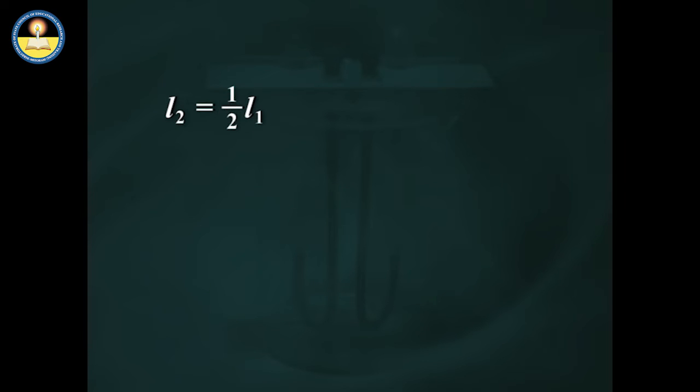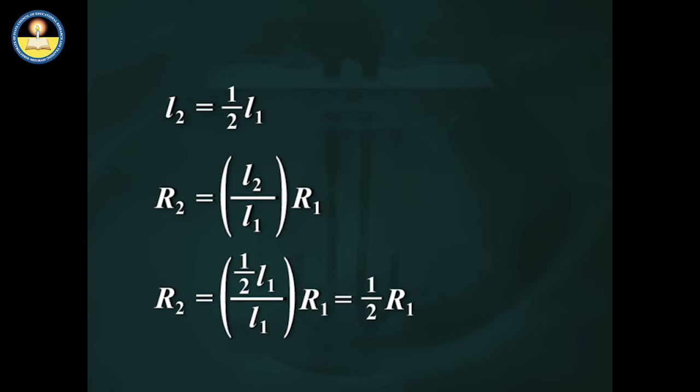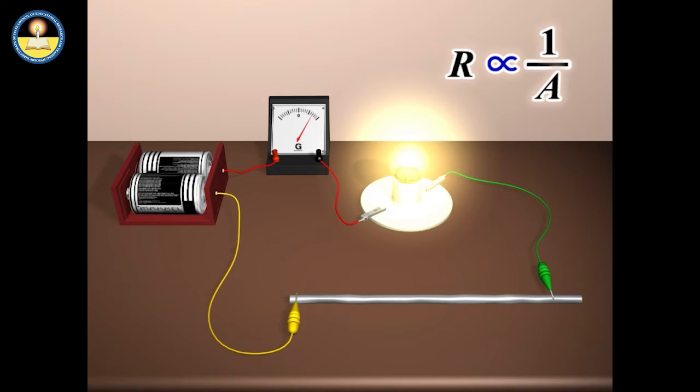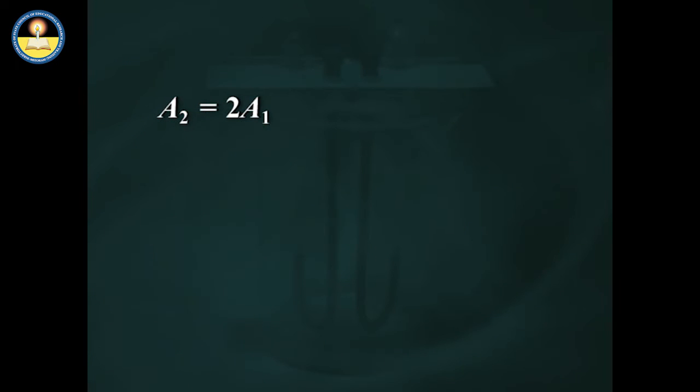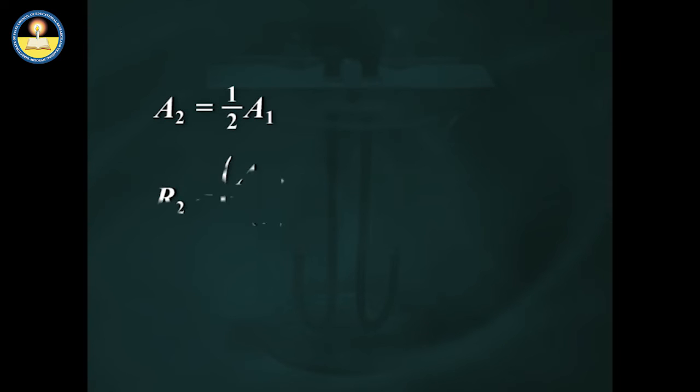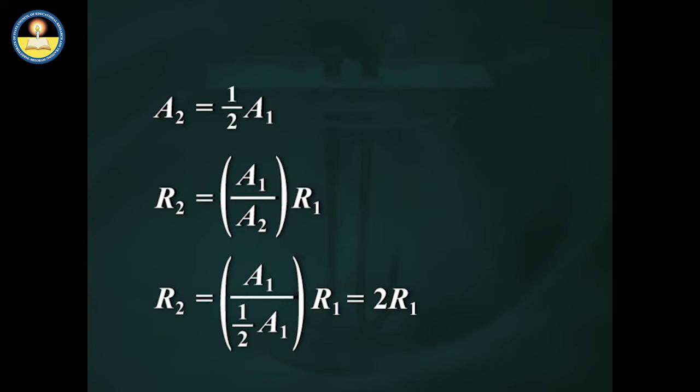Here, the resistance is 500 ohm. Time of flow of current is 30 minutes. That is 1800 seconds, and the potential difference is 220 volt. By using the appropriate relation, heat energy produced by the immersion rod comes out to be 174.24 kilojoules. In terms of calories, it comes out to be 41.684 kilocalories.